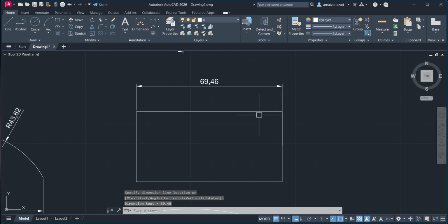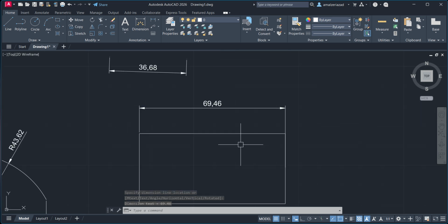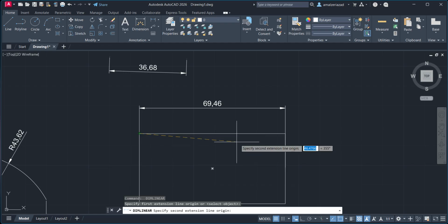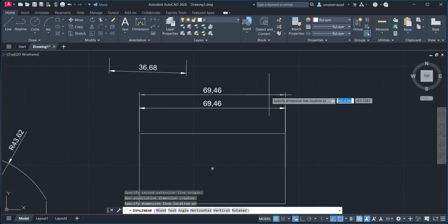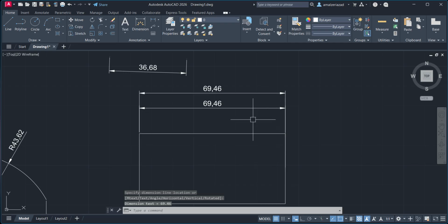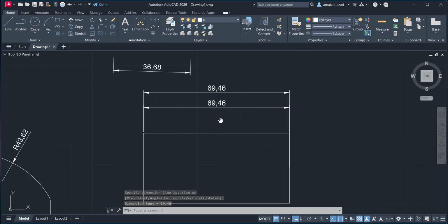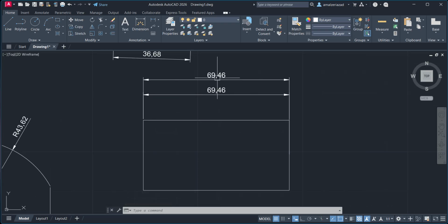If you go for other 3D modeling software such as SolidWorks and CATIA, if you give an extra dimension, it will show you a driven dimension, which is over defined. But here there is nothing like that, because as I told, it's a driven dimension. It is least bothered about how many dimensions you give. It is your responsibility to give each and every dimension. So we can still call this a drawback in AutoCAD.